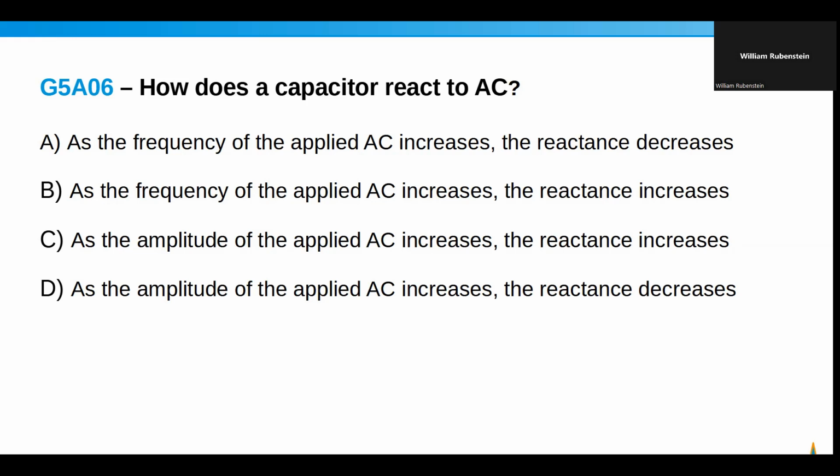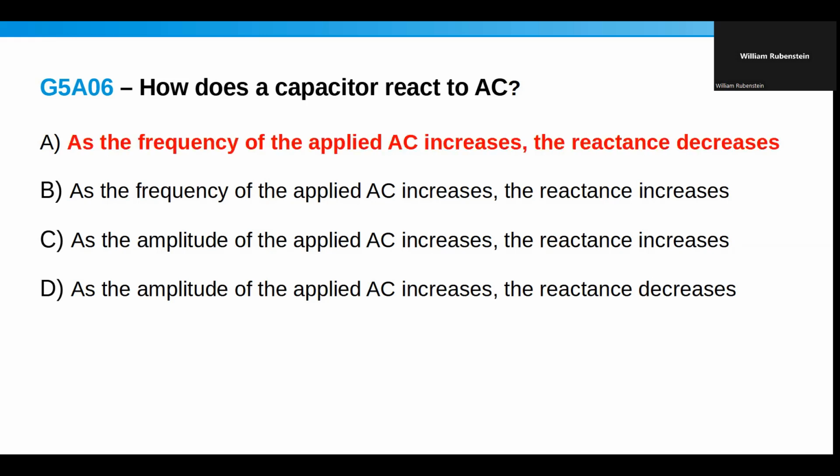As the frequency increases, the reactance decreases. It's the opposite of an inductor. Inductive reactance goes up, capacitive reactance goes down. And these two, amplitude has absolutely nothing to do with reactance. Strictly frequency dependent.